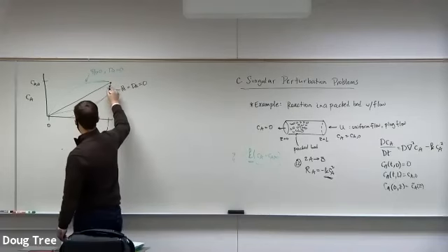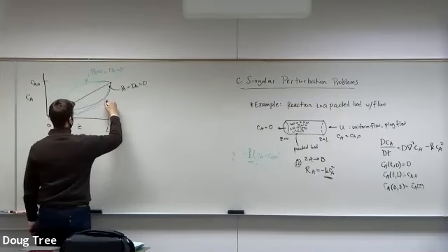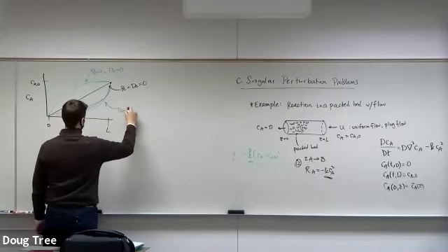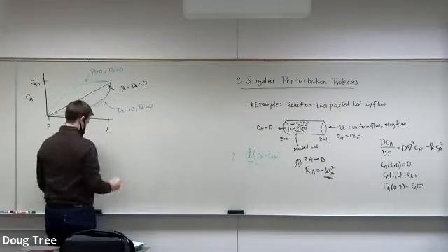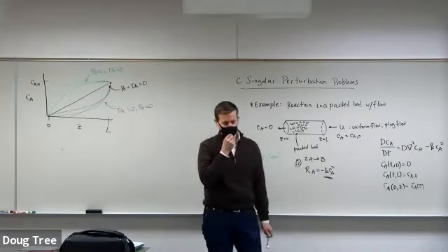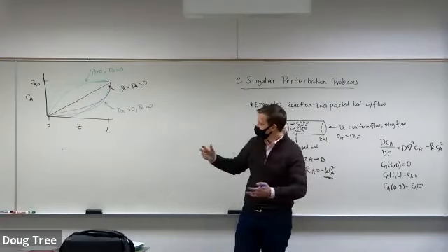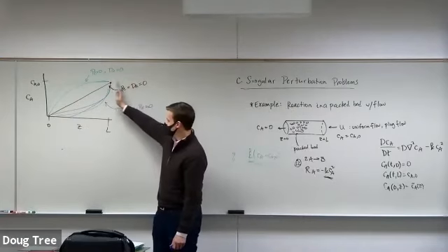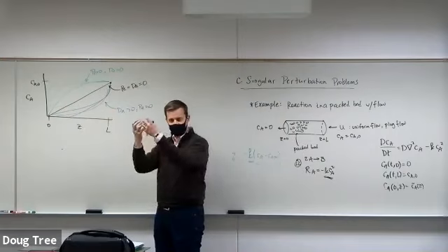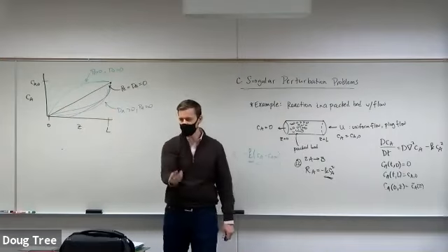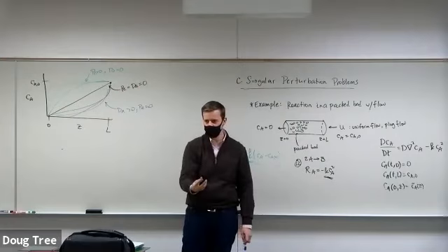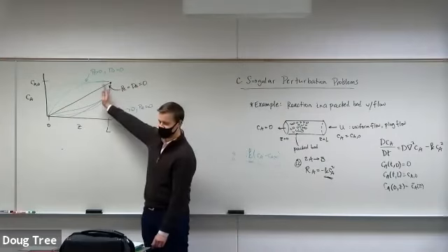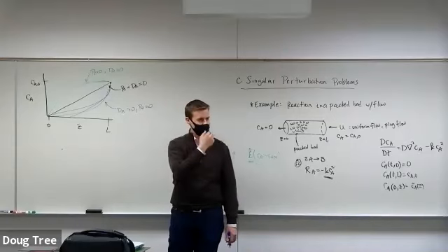So if the Peclet number has it above the line, then Damkohler is probably going to have it below because it's consuming concentration. Oh, yeah, it's consuming, right? So it's going to have to go like this. So this one will be the Damkohler number greater than zero and the Peclet number zero, right? So if I've got reactions, as soon as I get exposed to there, I've got extra stuff pulling C_A out of solution, turning it into B. So I'm going to have less concentration than I would with just pure diffusion.